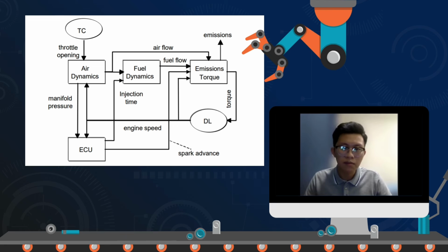The in-cylinder process for torque and pre-catalyst emission estimation has been characterized using black box neural network models. Based on the synthesis of steady-state experimental data, due to the requirement to limit the computing time with adequate precision, an engine control unit module, which is an ECU, has been developed in order to simulate the effects of different control strategies. The main objective here is air-fuel ratio control in order to guarantee optimum catalyst performance, especially in control transients because of the different dynamics of air and fuel flow.